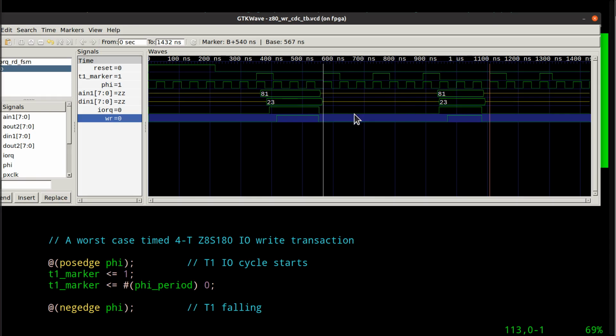In this particular application, the reason I do this is because when I'm evaluating the modules under test, they have operations to do as a result of an I/O operation. Then they're clowning around with stuff like that before they're ready for another I/O operation to take place. So I wanted to have a test bench that had the right amount of clock ticks specifically between these two operations to make sure that I had enough time, enough clocks in my circuit that I'm modeling to finish its job before we get over here. All right, so that's why I wasted that time.